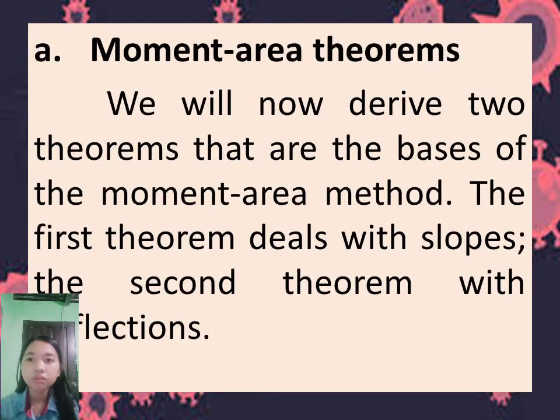The statical or first moment of area, or Q, simply measures the distribution of a beam section's area relative to an axis. It is calculated by taking the summation of all areas multiplied by their distance from a particular axis, or area by distance.